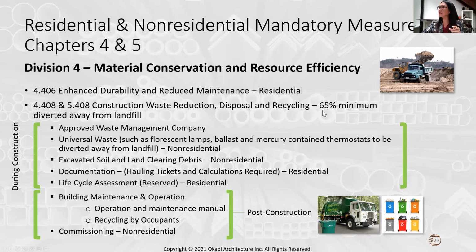And how do you prove it? Make sure it's in your spec. In the spec, we say you need to show me the waste management company and their annual diversion rate away from the landfill. The number they should disclose yearly, and it's usually registered with the local city. So that's one: a qualified waste management company.